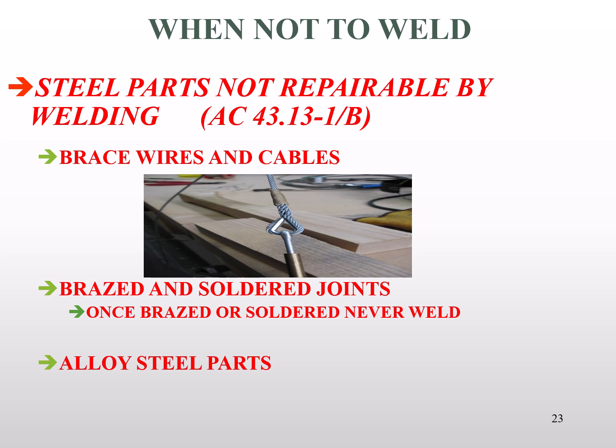Cables and cable fittings, it is not acceptable to weld. Once again, most aircraft cables are made of steels that have gone through a heat treatment. Therefore, if we weld them, we will destroy their strength properties. Also, once again, just to reiterate, brazed and soldered joints, it is never acceptable to weld behind those methods. If they were made by soldering or brazing, they must be repaired by the same methods, same techniques and materials.